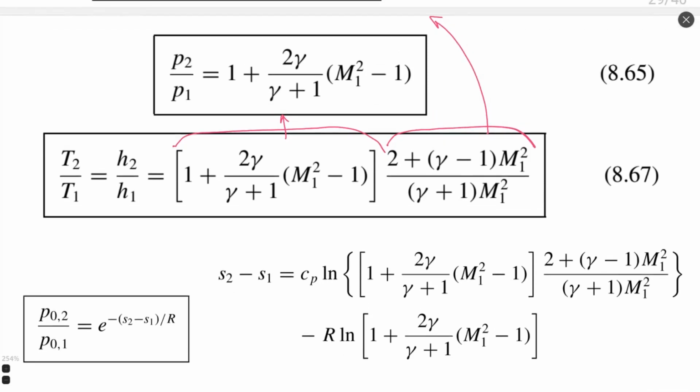Before showing you appendix B and discussing it, I would like to tell you also about the efficiency, or losses. In gas dynamics, losses of flow can be expressed as a ratio of stagnation pressures before and after some process. For example, before the shock wave and after the shock wave. We have to divide one by the other.